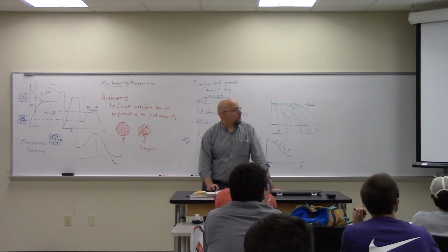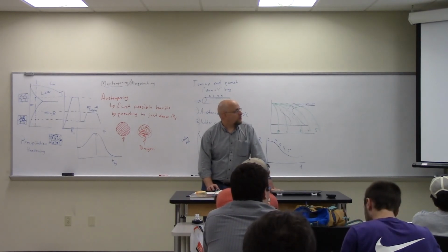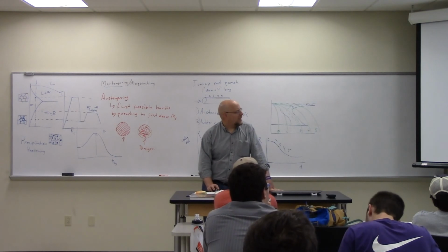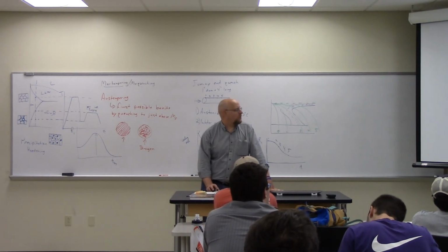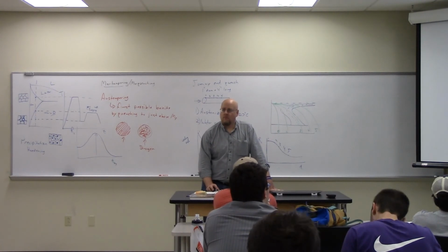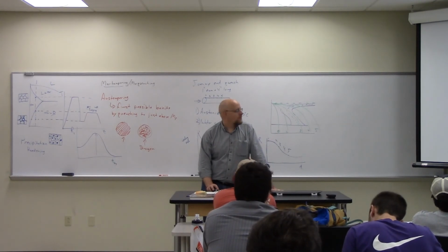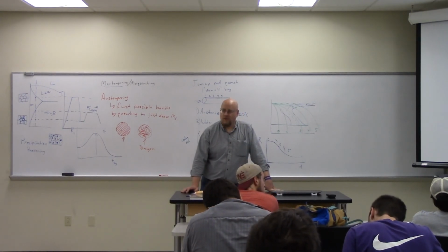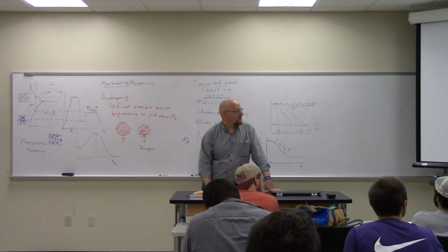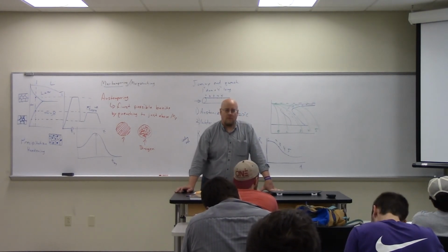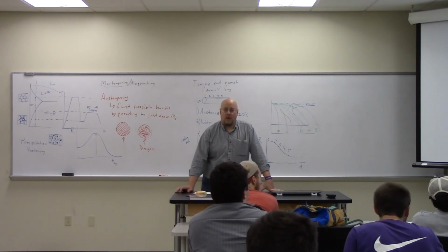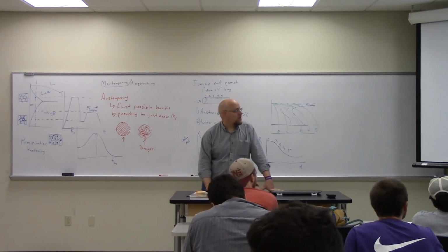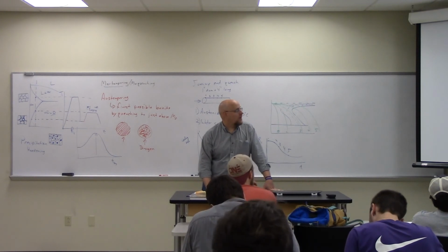Part B, what is the temperature at which the phase transformation would first be observed? What's the temperature at which it will first be observed, approximately? Okay, so right there, in the neighborhood of 670, 679, or 669. Okay. And what material is going to be formed? Still coarse pearlite, right? Still going to be the same coarse pearlite.